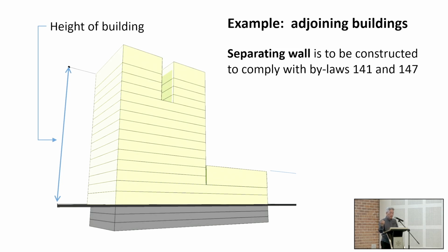We're talking about perimeter fire appliance access way. Those things are by volume. We're talking about the provision of firefighting shafts, provision of risers. Those things are irrespective of purpose groups. So your building height definition and the height to the topmost floor is very critical.